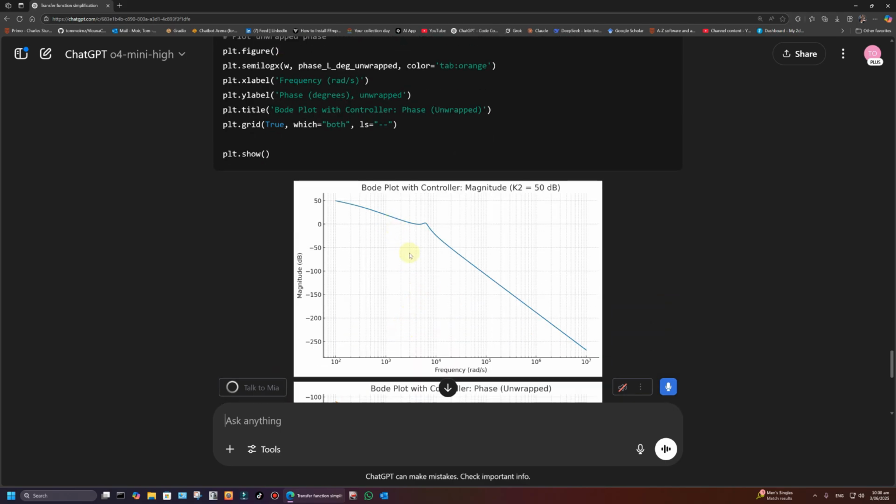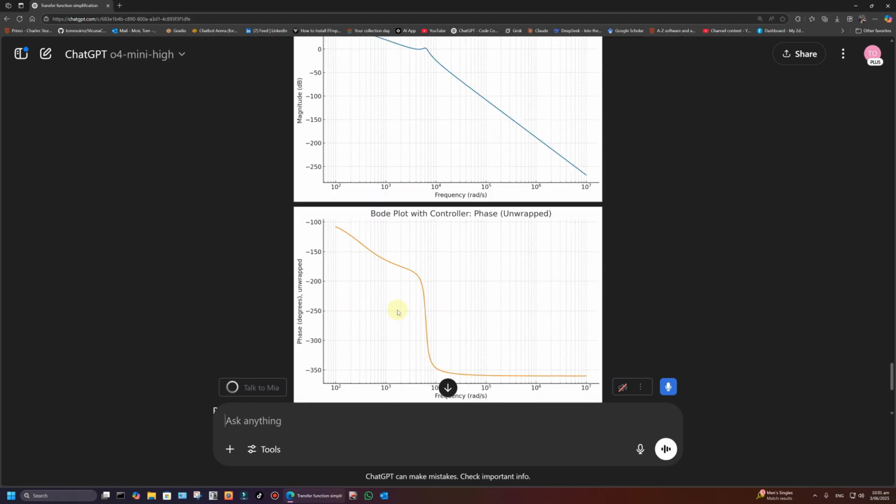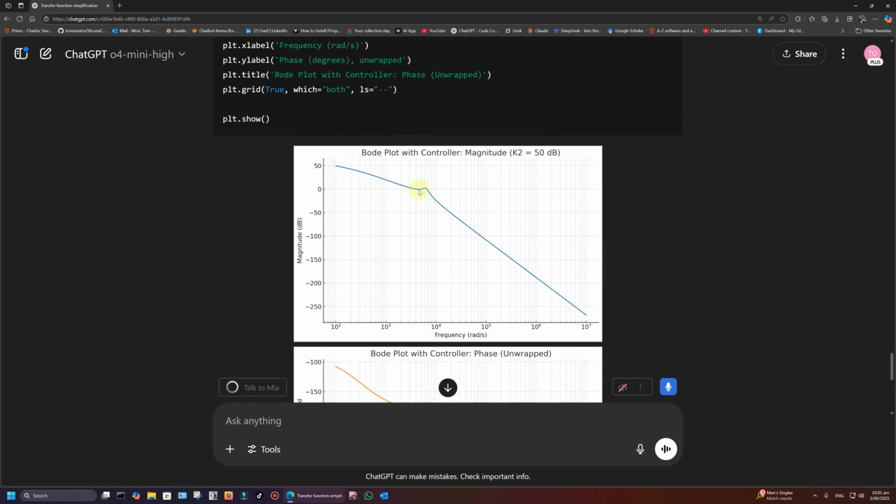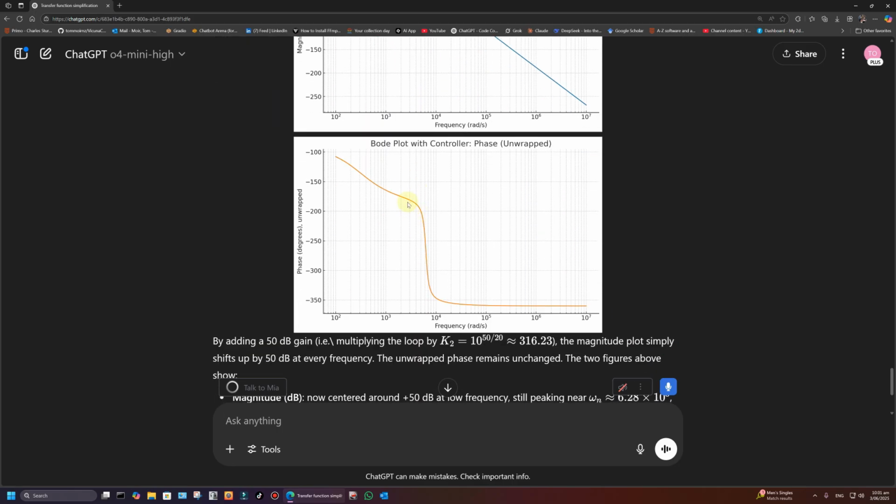Oh, that's nasty. So I can see that's my new Bode plot. It's going to be pretty horrendous. Actually, that's unstable. You can see from here, if I consider this as the crossover frequency, it's got a phase margin of minus, well actually maybe minus 180.